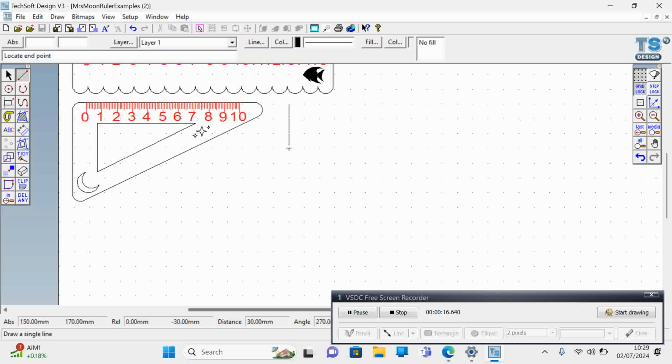You're going to drag down to 7 centimetres, that's 70 millimetres, and remember you can see that in the bottom under rel over here. It'll show you the rel. Okay, so 70, then I want to snap to this grid and I want it to be 140. So make sure you're watching that rel. I can see it's 140, snap to grid.